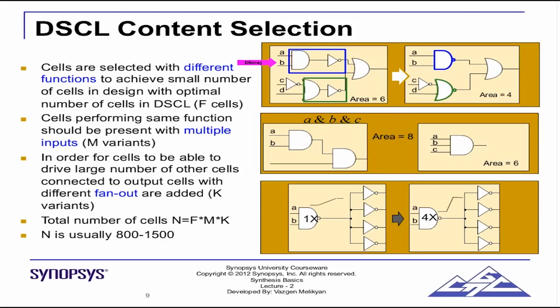But obviously, a cell with a weak driver at the output will not be able to effectively drive multiple fan-out, a lot of nets, right? So the cell has to be strong. How do we make cells strong? By increasing the W by L ratio of the output stage, by having multiples, by having a strong inverter at the output stage. So we should have some cells which can effectively drive high fan-out.